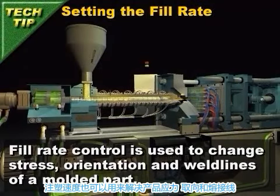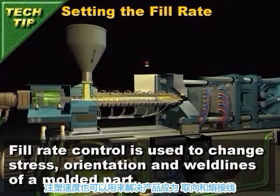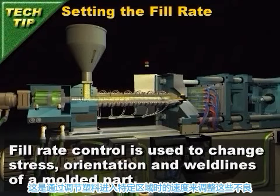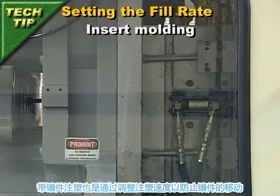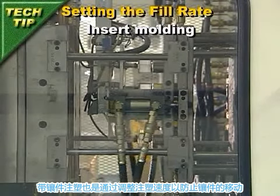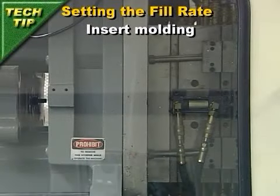Fill rate control is also used to change stress, orientation, and weld lines in particular regions of a molded part. This is a trial and error procedure in which the plastic flow rate is changed as the plastic first passes through a critical area of the part. Insert molding often requires that the fill rate control system be used to reduce the force of the flowing plastic against the inserts so they are not moved out of alignment during mold filling.